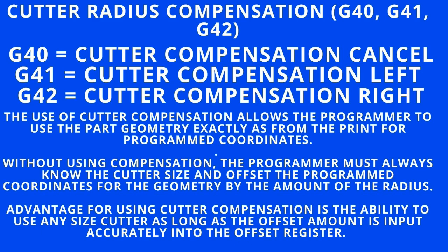Why should we always use cutter compensation? It allows the program to use the part geometry exactly as from the print for program coordinates. If we are not using cutter compensation, each and every time the programmer knows the cutter size, and he has to put the offset in the registers.